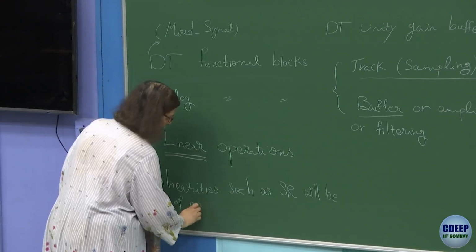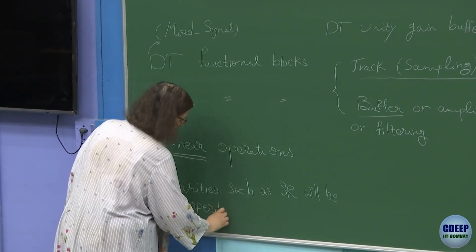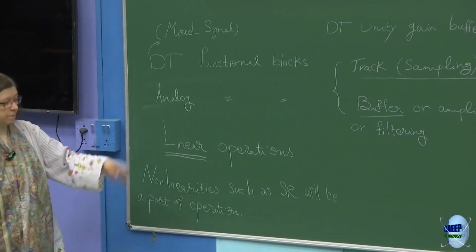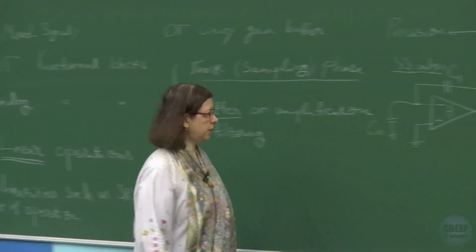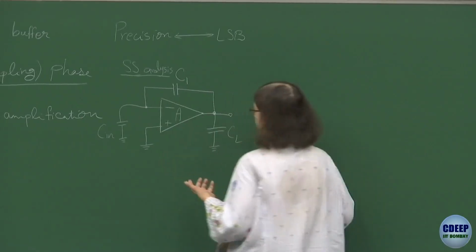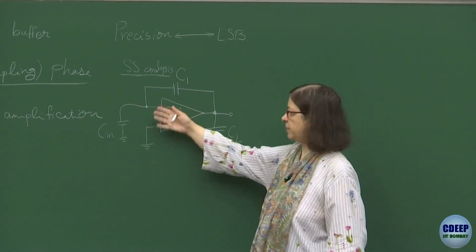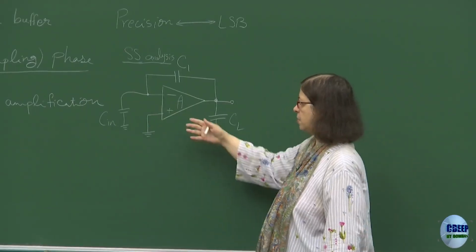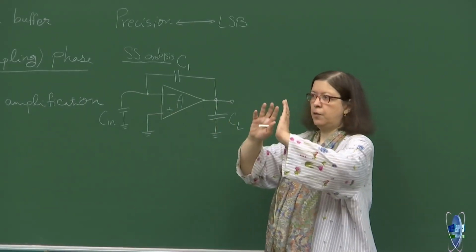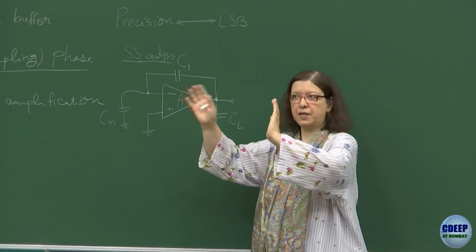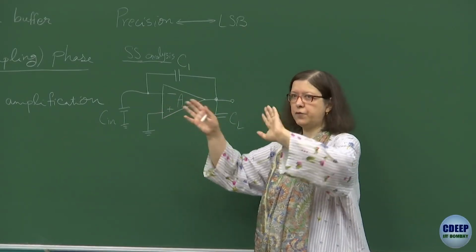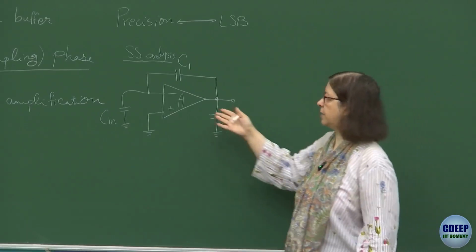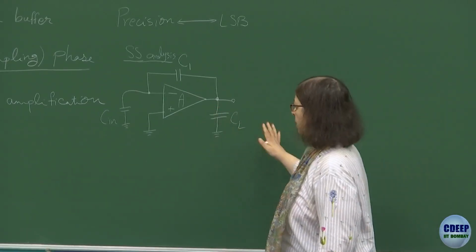In fact, the beginning of this buffering phase was a nonlinear phase. The op-amp was going into the nonlinear domain because the input of the op-amp suddenly rises to a very high differential value. So at the input stage of the op-amp, one differential half circuit will be off, the other one will draw the entire tail current, and the circuit will get into a slewing mode.